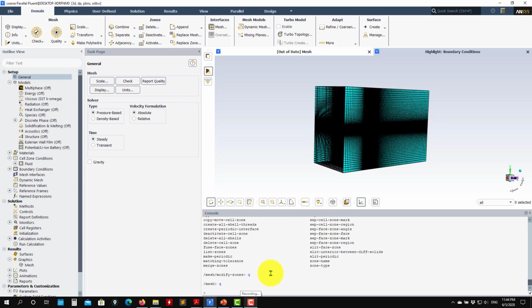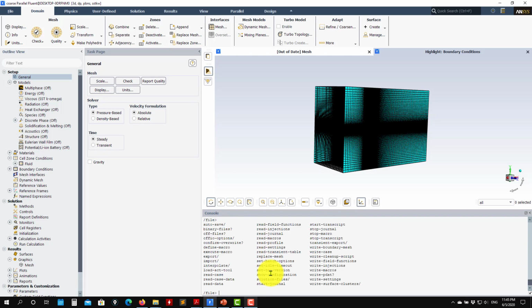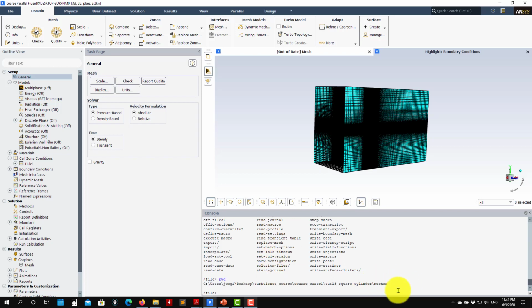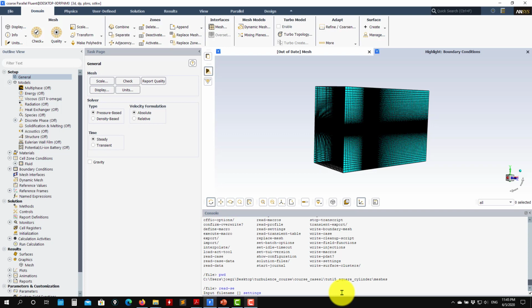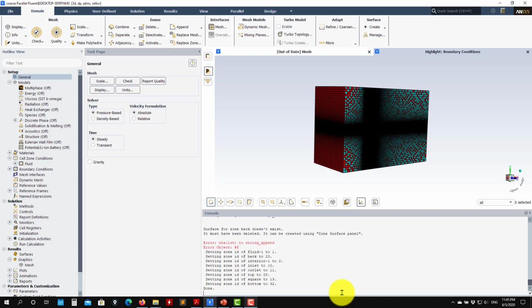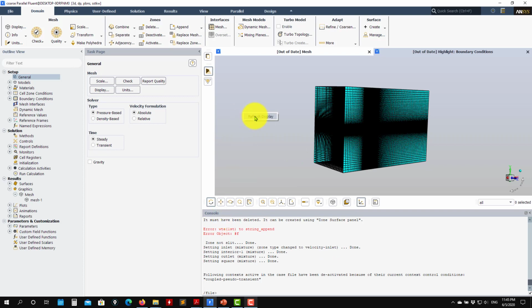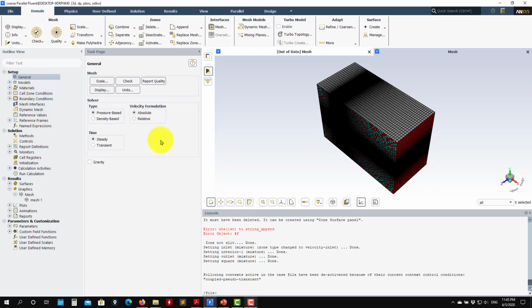When you go back in Fluent, you go here, Q, and then File, Settings. First you need to have the file in the working directory. To know the working directory, you type pwd, and it will tell you that you're working in this directory. See that here you put your settings files. You go read settings, and then settings runs, and see that it read the settings file. There are a few errors where it doesn't matter, but then you can correct whatever you have.